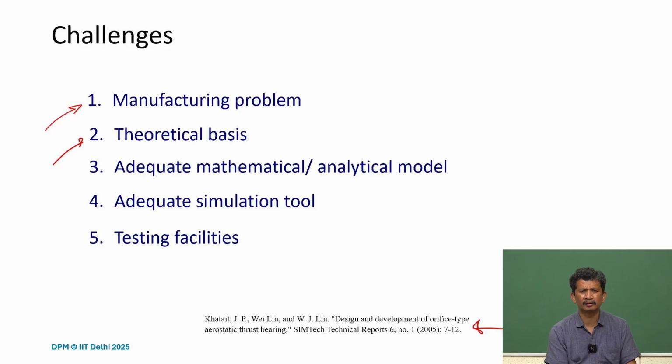If we have complex geometries, for example rectangular blocks or a rectangular pad with annular grooves, the theoretical basis might not be there, and we may have to resort to different kinds of numerical methods or CFD tools for the studies.